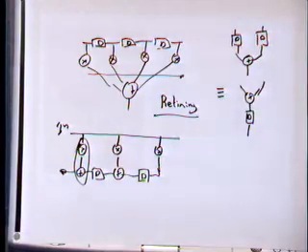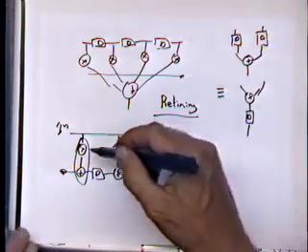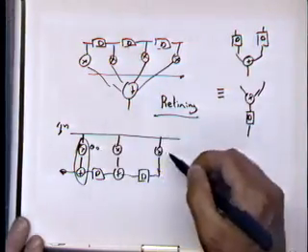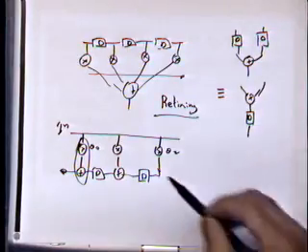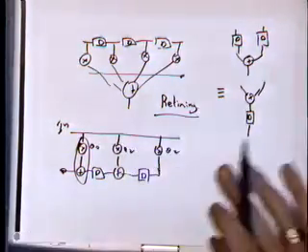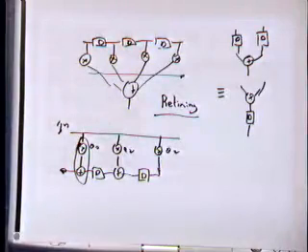So, gee, there's too many adders in a row, so can we reshuffle them a little bit? As you can see, obviously, if this is A0 and A2, they're basically the same, so I have to compute it only one time. And A2 is half of that. So I can actually simplify that set of multiplications quite nicely and save adders as a result of this.